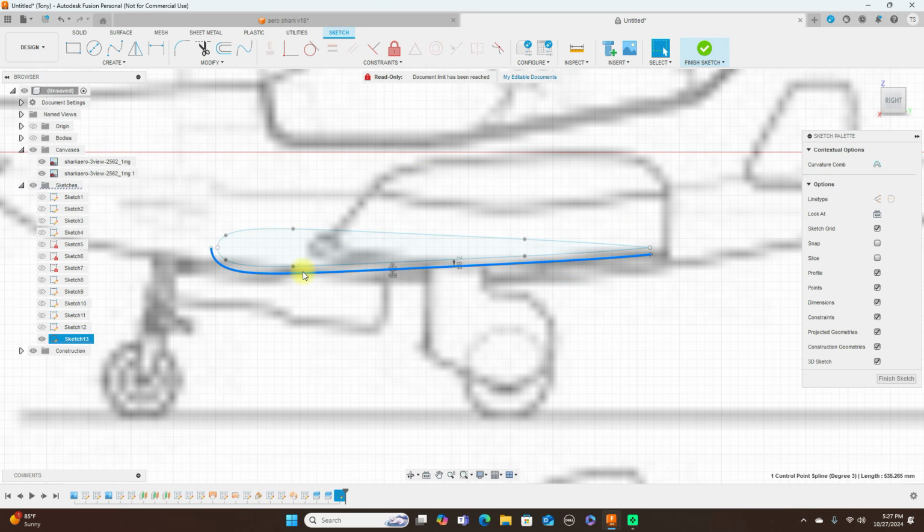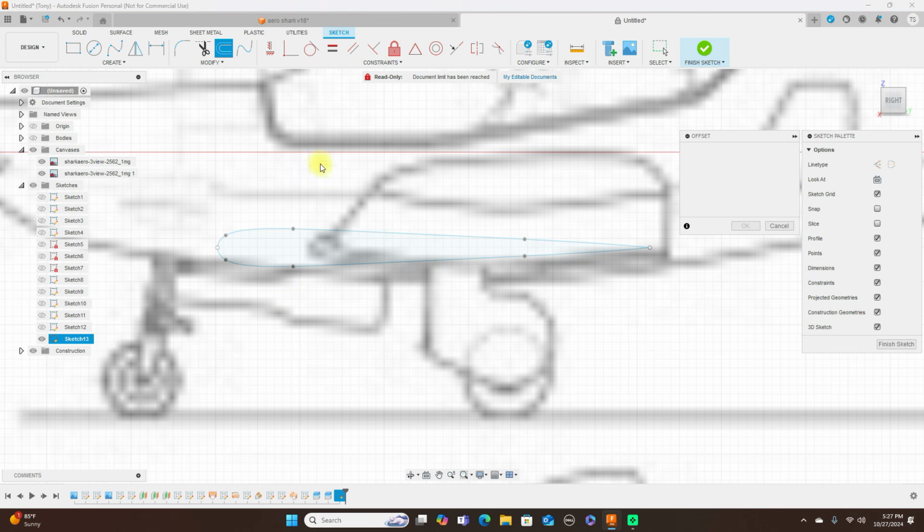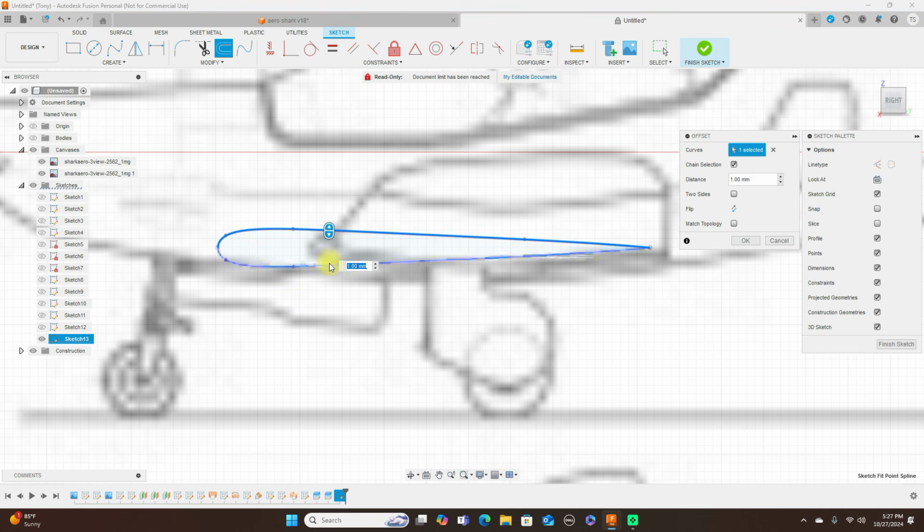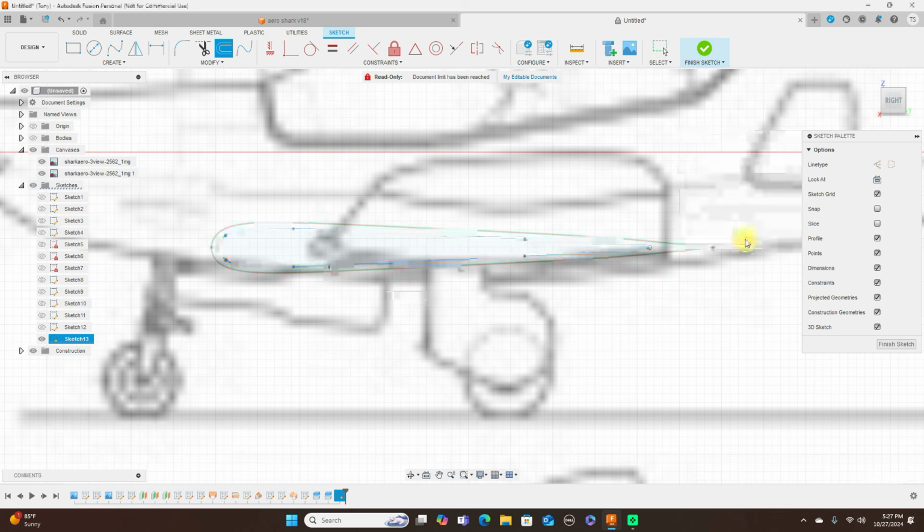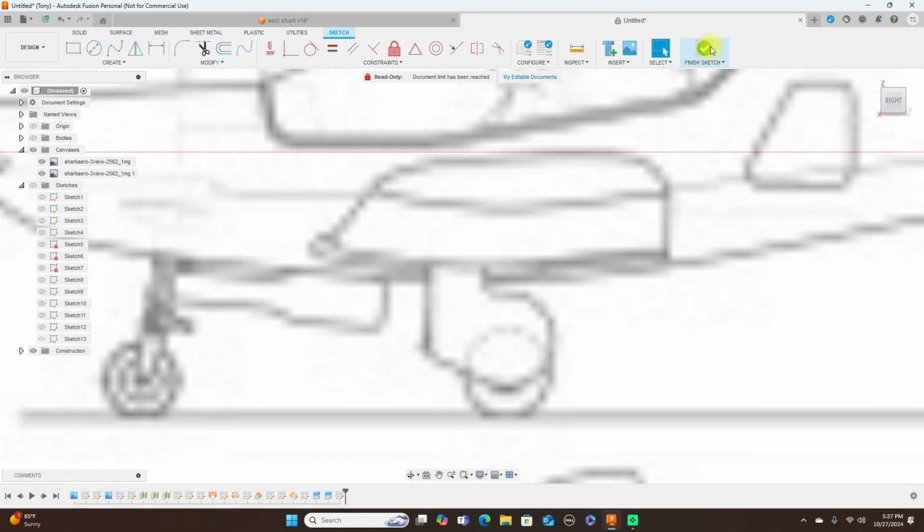And cancel this. And do an offset. Click OK. Go ahead and finish sketch.